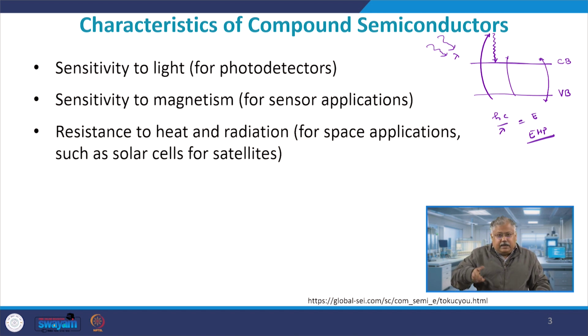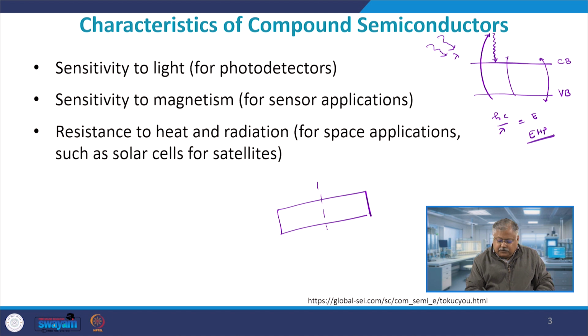How is it done technically? You can actually use a PN junction to do that photo detection. If you have this depletion region here, the depletion region will be exactly equal on both sides. The depletion region is devoid of any free charge carriers, but when light falls onto it, there will suddenly be a large amount of electron hole pair generation.